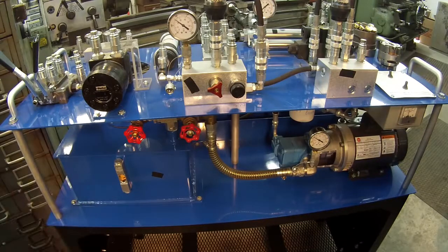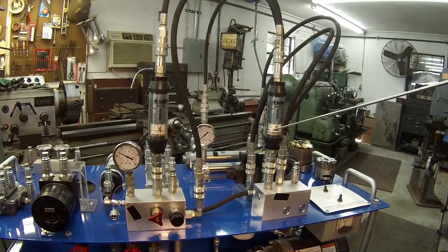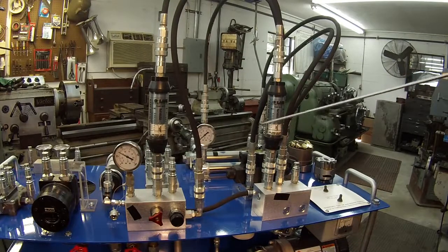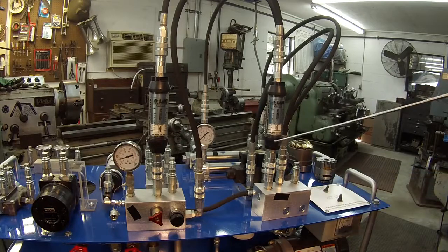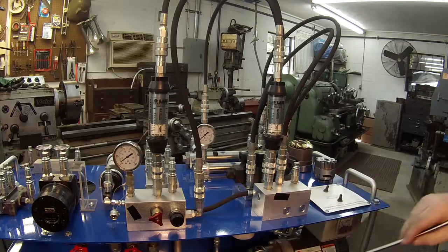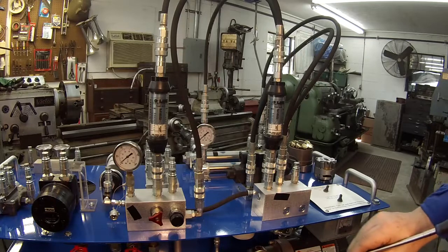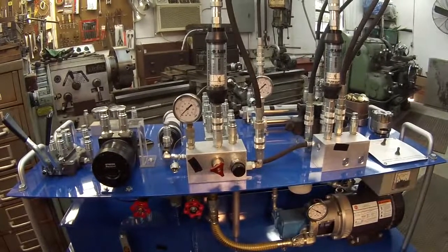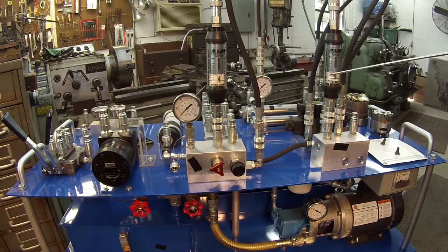Alright, you see my flow is dropping off right here. And the reason my flow is dropping off is because, remember I told you oil is incompressible? What I've done now is add air into my oil, and you see all this foamy stuff right here? That's because the oil is now mixed with air, and my oil has become compressible. So that's the reason my flow dropped off. This pump now is not pumping oil anymore, it's trying to pump air, so it just stops pumping. And you see your flow drop off right here.